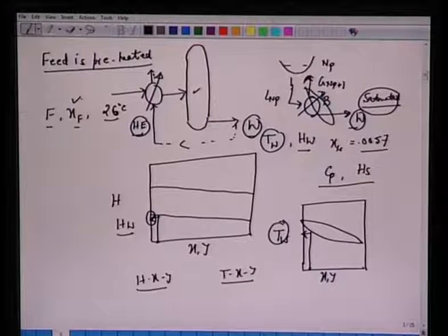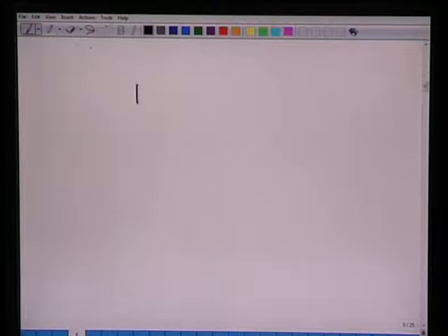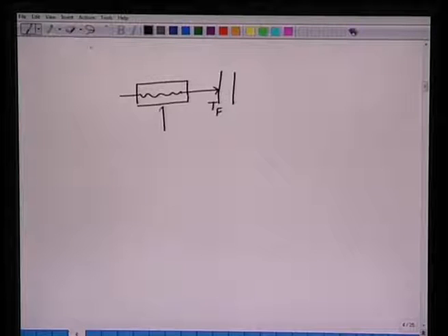Now let's come back to this heat exchanger, because we have to find the temperature of this feed which goes to this distillation column. Here we have W. We calculated the flow rate of this W, which was 132.4 kilomole per hour. Since we calculated the molecular weight of this bottom product, multiplying by the molecular weight, one can also calculate the total mass flow rate, 2396 kg per hour.